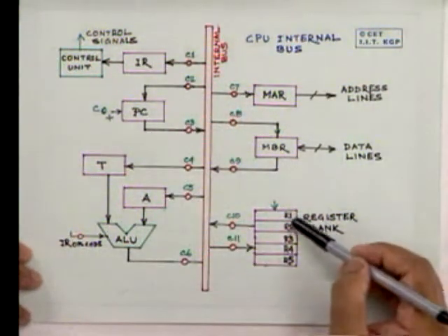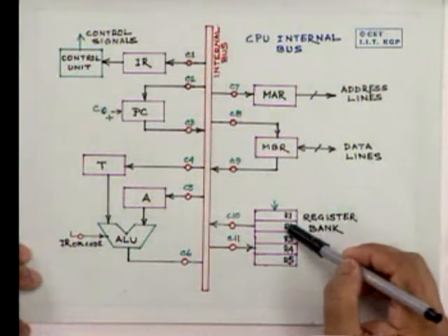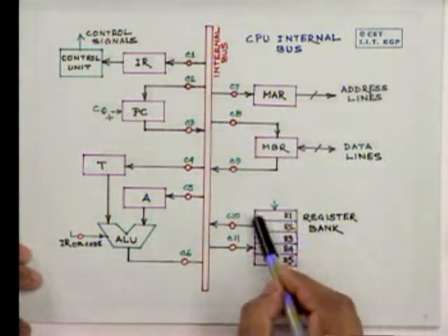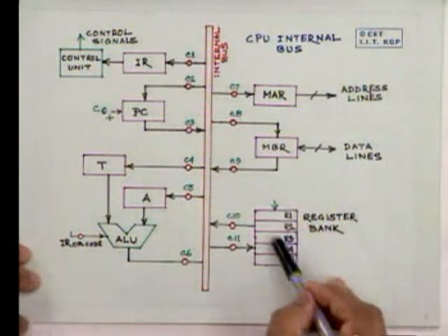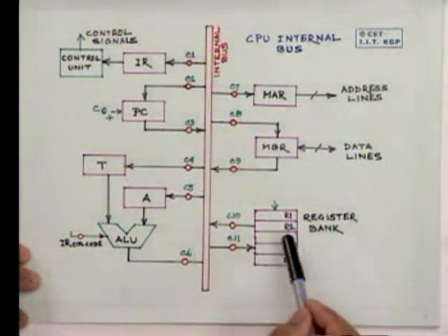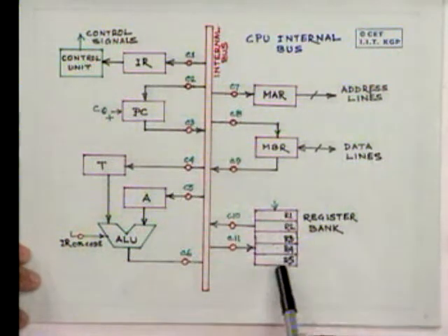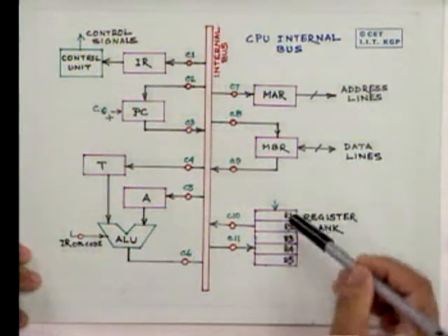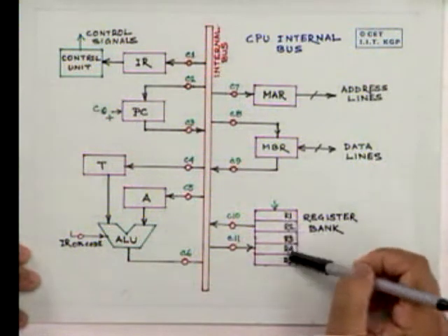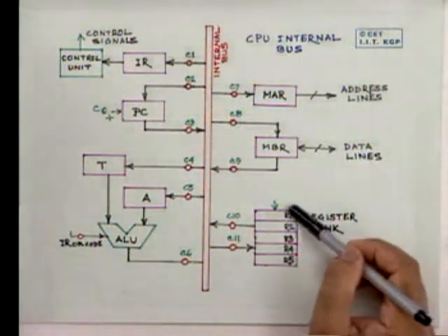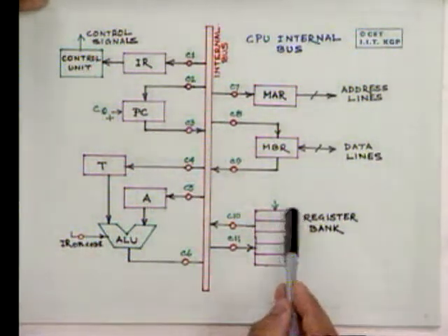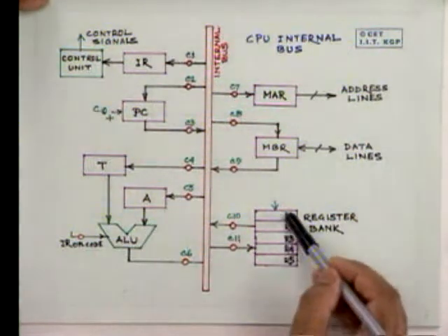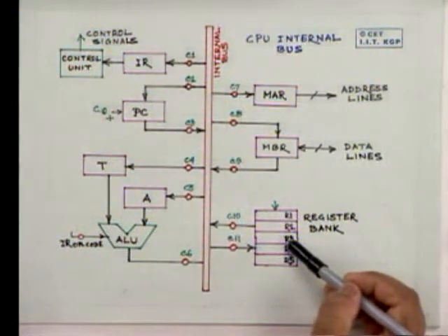Which means that, for example, if you want to transfer R1 to R2 or say R3 to R4, there is a multiplexer which will automatically take the input from R3 and load it into R4. That is done very fast, and we need that to be done very fast, and therefore there is a multiplexer circuit through which the data transfer takes place within the register bank. We will be assuming this picture over here. And in most CPUs, the general purpose registers do exchange data that way only.